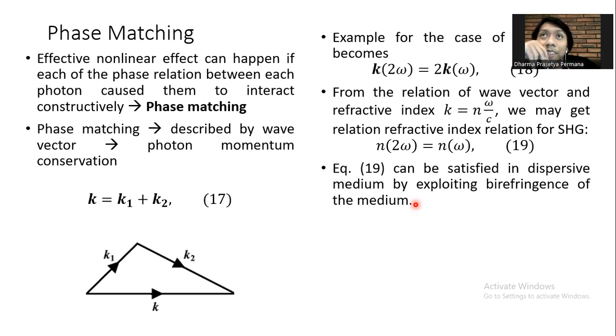Even one material with the same quality and the same waveguide may produce different nonlinear interaction. For example, in my case, doing four wave mixing, I use silicon nitride. Silicon nitride may have a different quality of nonlinear interaction depending on how we fabricate it. Let's say we fabricate it using low pressure chemical vapor deposition, LPCVD, and another way is plasma enhanced chemical vapor deposition, PECVD.